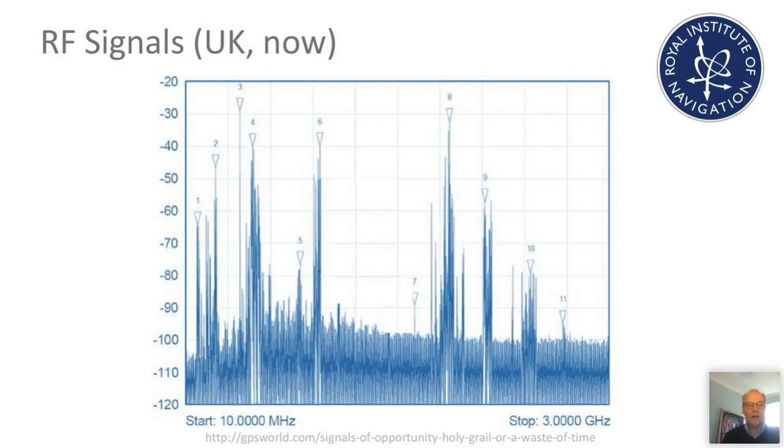Now just think for a minute how much closer Iridium is to the surface of the Earth than the GPS satellites. And you'll soon realize, well, where are the GPS satellites? The answer is you can't see them on a plot like this. The reason is that by the time those signals reach the surface of the Earth, the power level is below what's called the thermal noise floor.